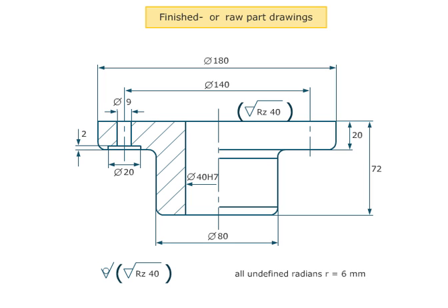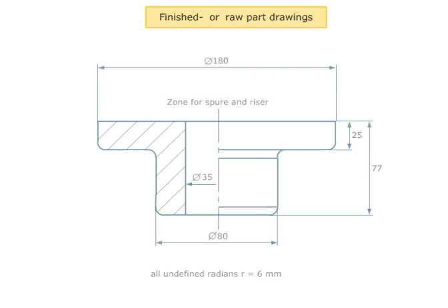The drawing of the casting shape is referred to as raw part drawing. The raw part drawing contains the allowances requested by the designer, machining allowances and drafts with all length, thickness, and angle tolerances, as well as the positions of sprue, also referred to as gate, and riser.